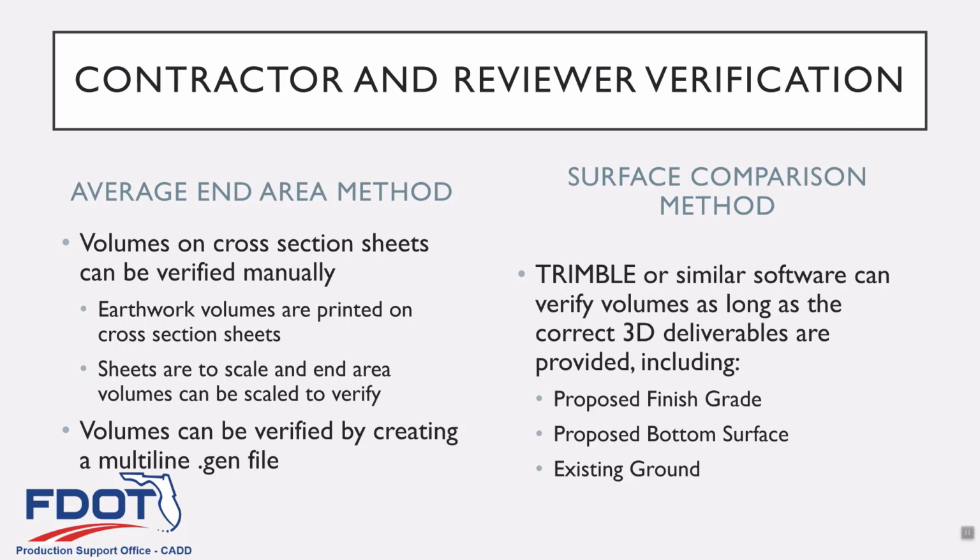So if you open it up in there and actually run earthwork calculations, it's presumably a different algorithm. It's the same method, I believe, but presumably they have different programming underlying it, so it's completely independent from OpenRoads Designer. So it's an independent check. It's a safe bet.